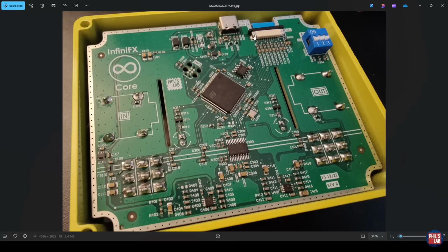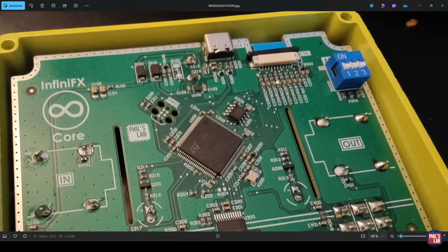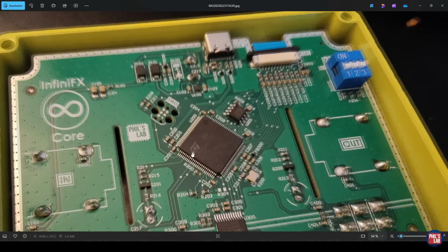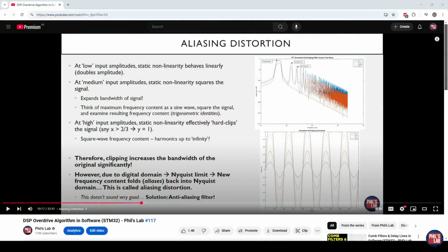Connections to the potentiometers are done via ADCs contained within the STM32 and these are connected via ribbon cable to the top PCB, which just has potentiometers on it. And I'm programming the STM32 via the serial wire debug connection using this very nifty Tag-Connect header and an ST-Link.